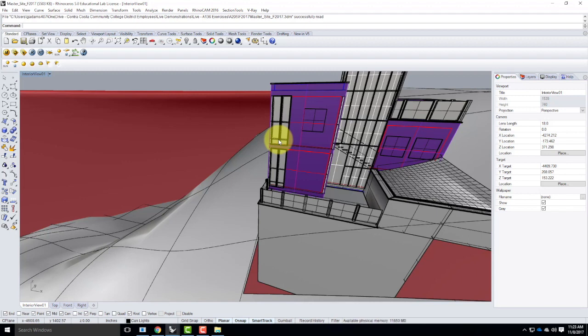One of the problems that people run into in the renderings, though, is that there's no surface outside the window for the light to spill out onto. So having a patio or a deck or something that you can include as part of the render makes the exterior night rendering better, because then there's something to reflect on. If your building is plunked down in the middle of a bunch of grass and you're trying to render out a night scene where you're casting shadows on grass, it never turns out quite that good. So having some kind of a solid surface to cast the shadow on can help.